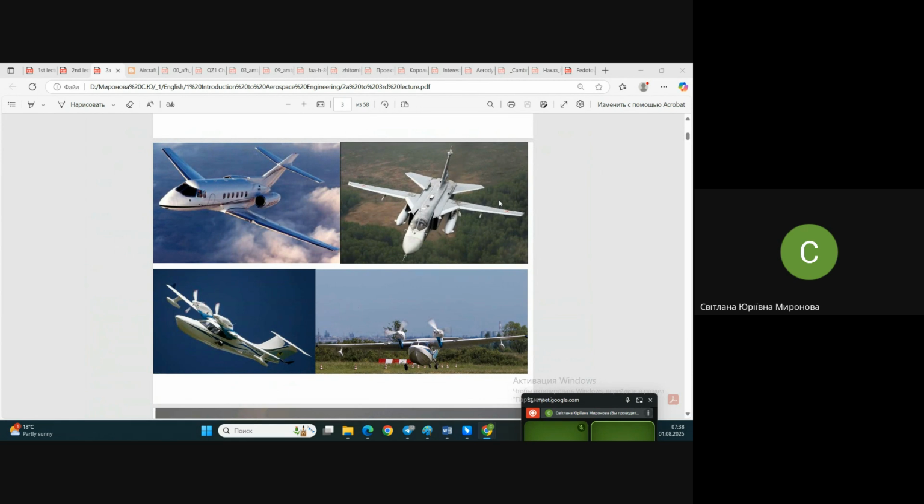Because I should say that those airplanes where you have any tricks like this, with changing of geometry during the flight, whatever they are, even flaps, for instance, these additional functions result in increasing the weight of the airplane. Because to rotate those things, above all, this place you need to make heavier, more thick, more massive. It's additional material. Additional material means additional weight.